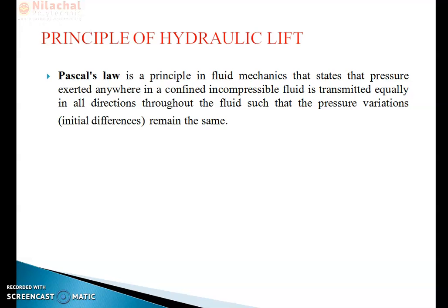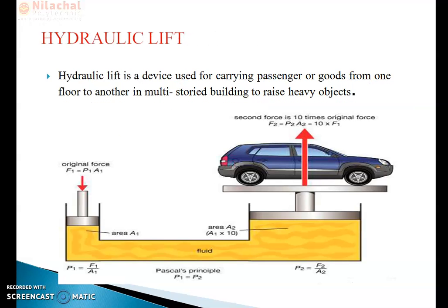That means the pressure exerted anywhere on the fluid. Now this is the confined fluid, and the amount of pressure you give here, the same amount of pressure will transmit everywhere in this system, and the pressure variation is the same throughout the system. So this is Pascal's law that the hydraulic lift follows.